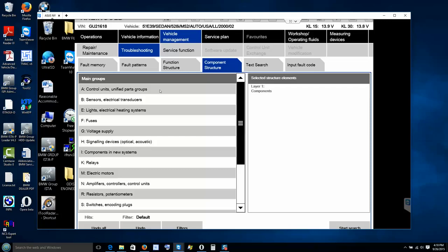Oh, I see what you mean. Because the electrons are flowing through the bulb that he replaced, right? Right, because the resistance is low, it's constantly streaming electrons, so it appears as if the bulbs are blown. Yeah, I see what you mean. So maybe you have to purchase ones that have the resistor built within them. That's what I told him. You're going to have to get different lights. Okay, all right, no problem.